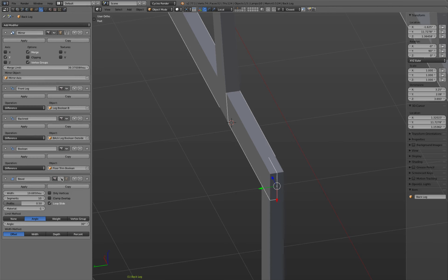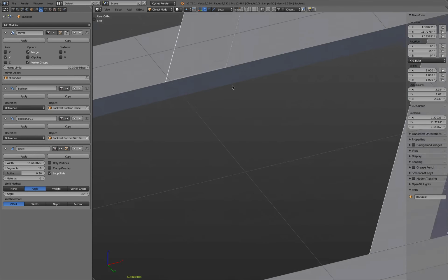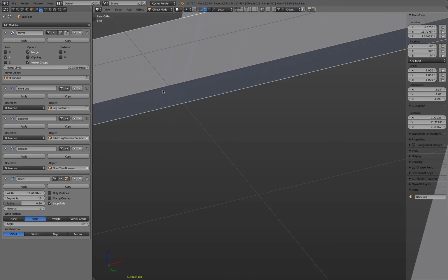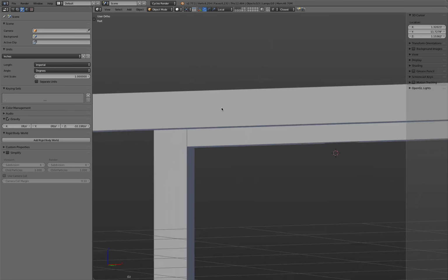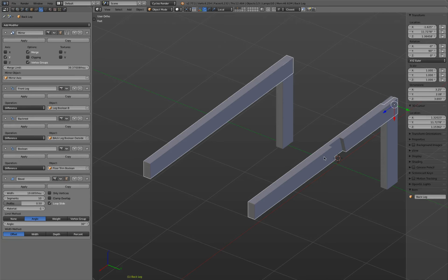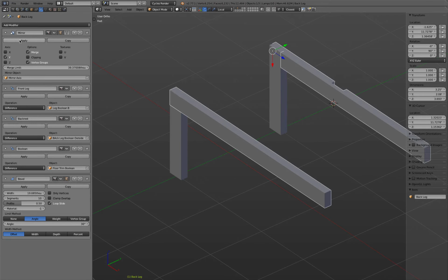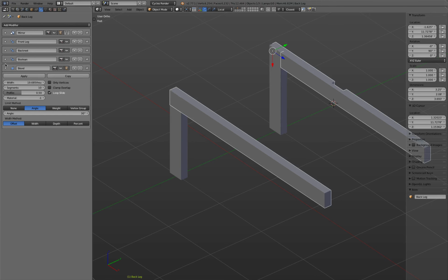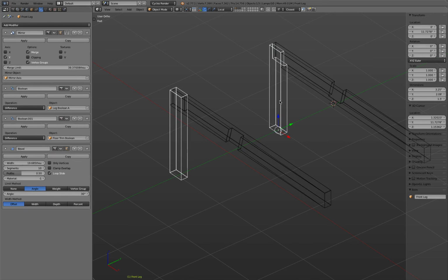Thankfully, because we have the bevel modifiers applied, we only hid them. We can reactivate them, so they're all back. The other modifiers are still working fine. What's going on there? Hold on one second, we might have to fix something there. Oh, interesting. What's going on here? Makes sense. You see, there is the modifier to cut it out, but not there. And that's because my mirror modifier is at the end here. So down, down, and down. Perfect.